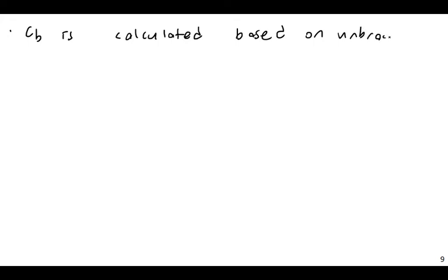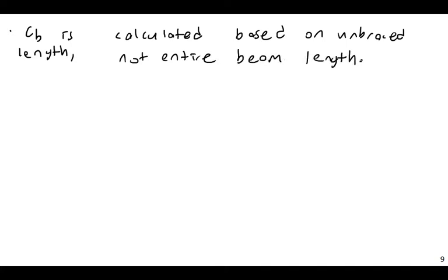CB is calculated based on unbraced length, not the entire length of the beam.